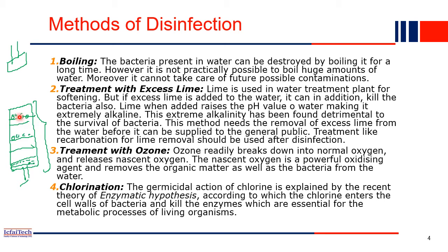Here at the top you have the big gravels, where all the large floating particles are simply retained, right. Then the filtered water goes to the fine gravels, where the fine solid particles are retained in this layer. In the last layer they keep the fine sand, similar to the filtration we do. After the fine sand, all the suspended particles are removed and you get crystal clear water at the bottom. So this is the homemade water treatment plant, which earlier even in rural areas they constructed similarly.